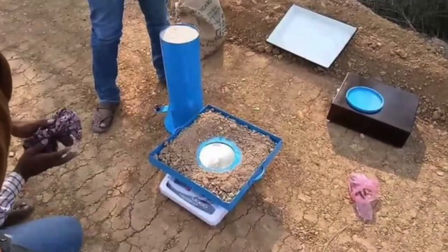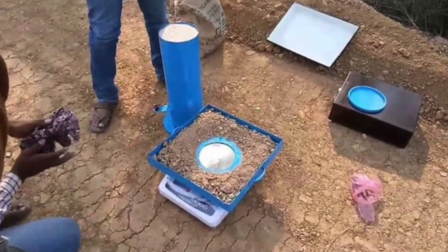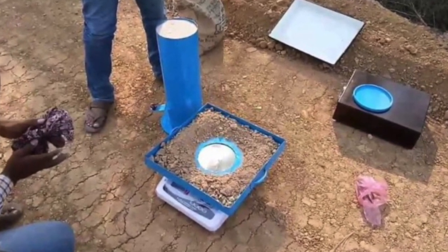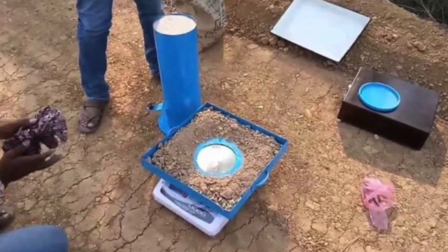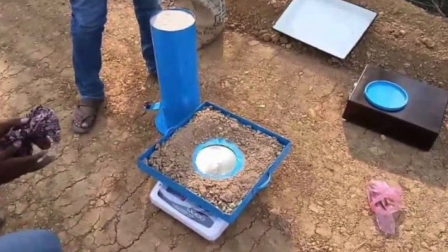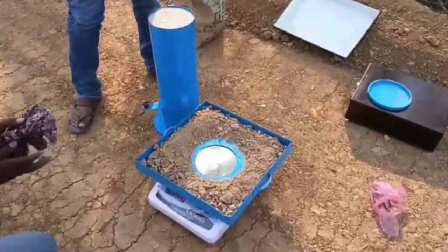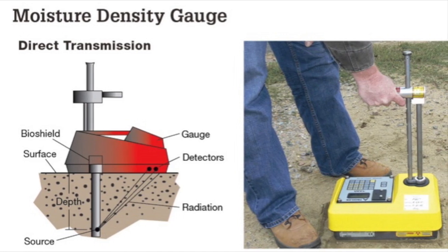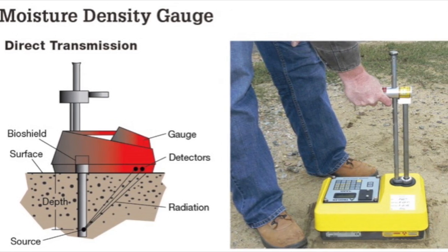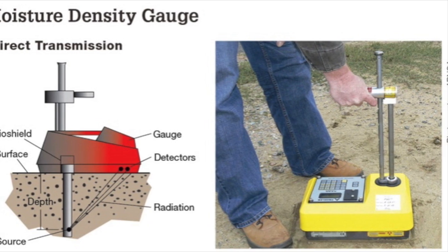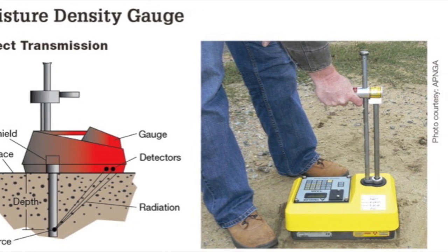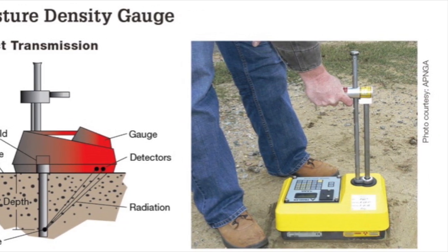For the quality control aspect then, we looked at the most common practice would be CBR and MCV values. These are very expensive means of calculating the correct density and moisture content values. It is more common practice to use a sand replacement test and a nuclear density meter to get your correct densities and values on site.